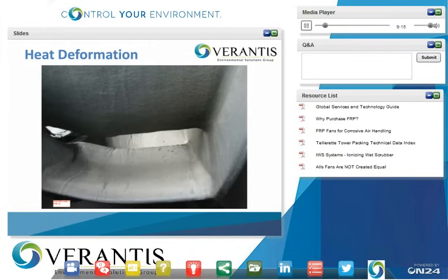This is showing the blade of a club impeller that has severe heat deformation. Heat deformation can be caused basically by 3 things. The first and foremost is your process temperatures. If there's an upset and the process temperature gets too high, you'll see this. Also, if you have a mesh pad mist eliminator before or after the housing, that can also cause heat distortion, or running the fan with closed dampers. And this heat deformation not only pertains to the fan, but it can also cause detrimental damage inside the scrubbers and ionizers.